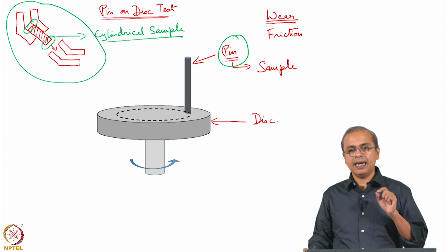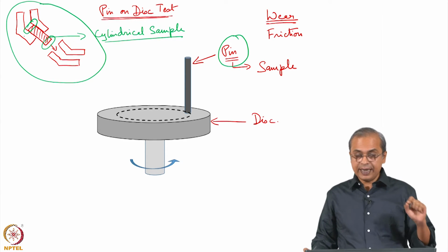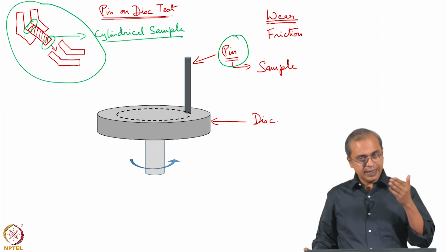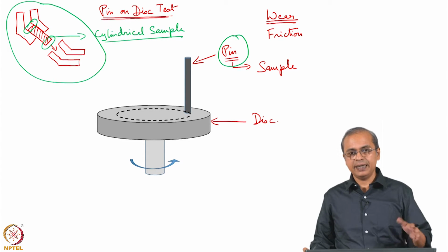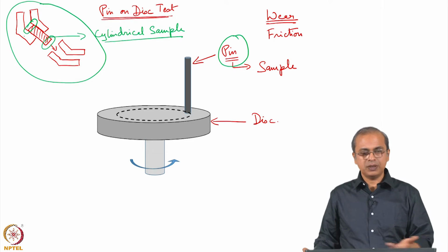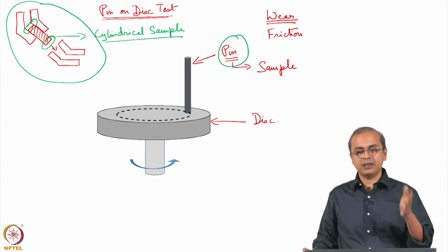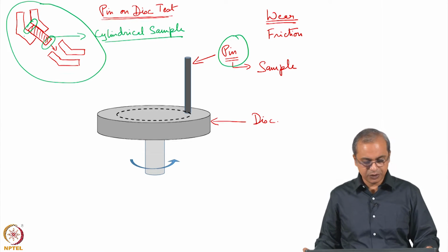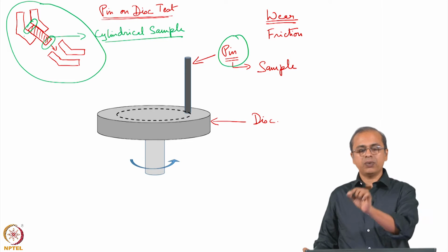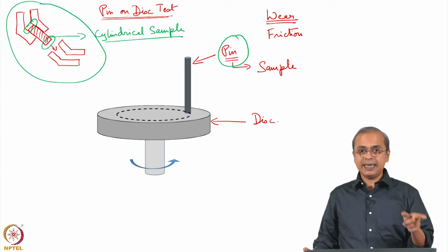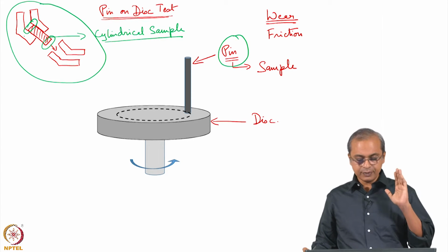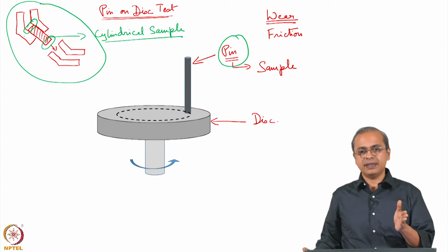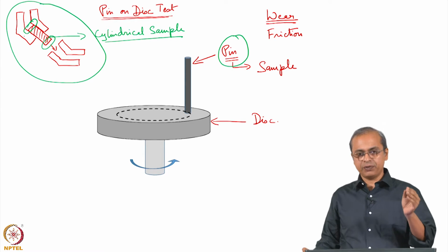Generally you are going to get a pin, and that pin you can get in microcrystalline or macrocrystalline form from some commercial entity, and then you can subject it to severe plastic deformation such as equal channel angular extrusion, and the same pin you can now get in nanocrystalline form. So, you can get the same sample in microcrystalline or macrocrystalline and nanocrystalline form, and that is what we are always interested in if we want to study the effect of the nanoscale.